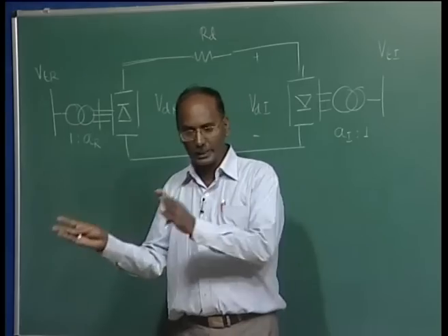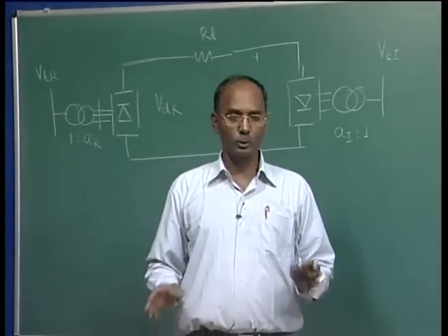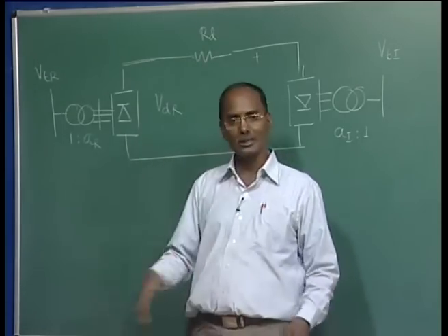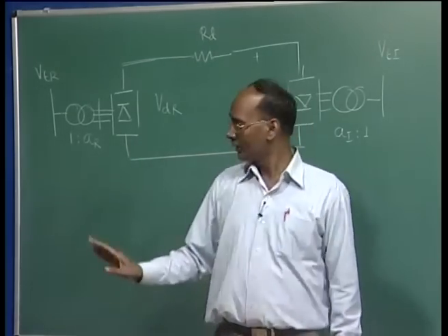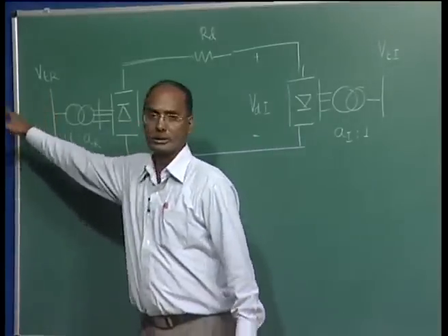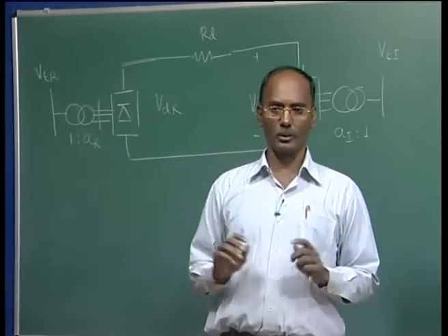If we used it in the AC power flow, your Y bus matrix would keep on changing. We do not want this, so we keep it on the DC side, because anyway we are solving the DC equations. On the AC side, at the terminal voltage, the network topology is fixed, your matrix is fixed, and there is no problem.